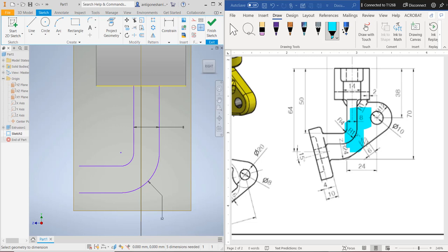When you have uniform thickness, this is a sheet metal concept, but I'm going to introduce it here anyways. Anytime you're doing a common radius on a bent object, sheet metal is where we can start talking a whole bunch of other stuff, but generally speaking, the inside radius is equal to the outside radius minus the material thickness.